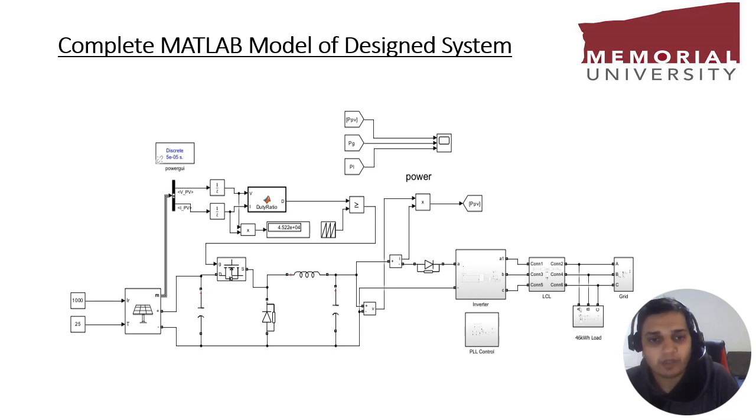And if you see that after MPPT the output signal is fed into the MOSFET gate input. The signal from the MPPT will just control the current we can get from the solar panel, to maintain the maximum current from the solar panel. Then this DC signal is fed into the inverter, and in the inverter we are using the PLL loop control.